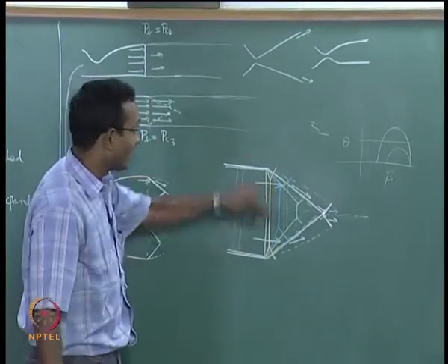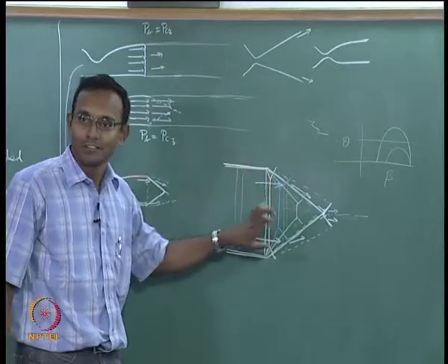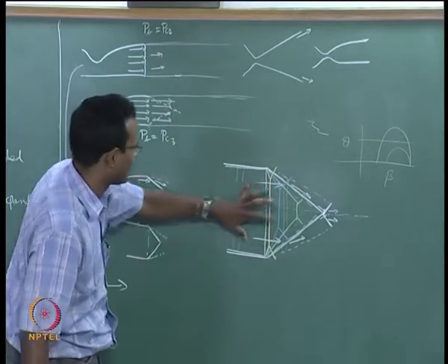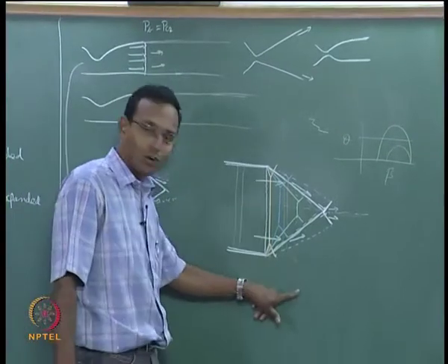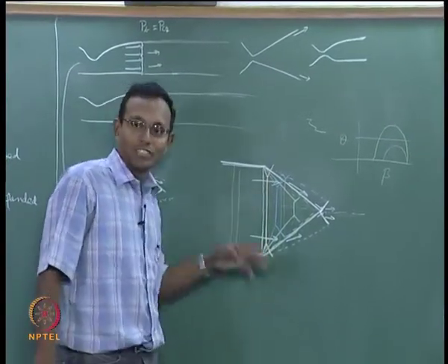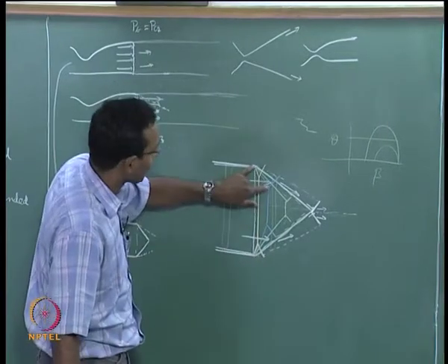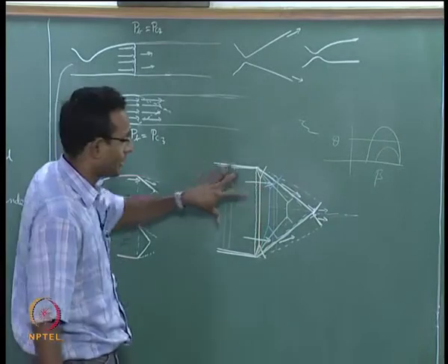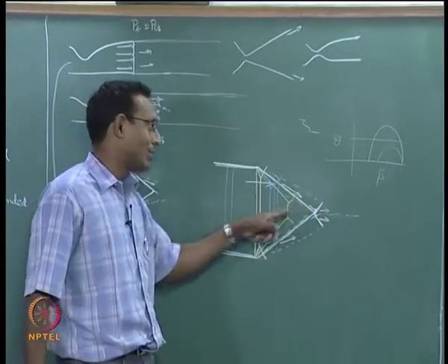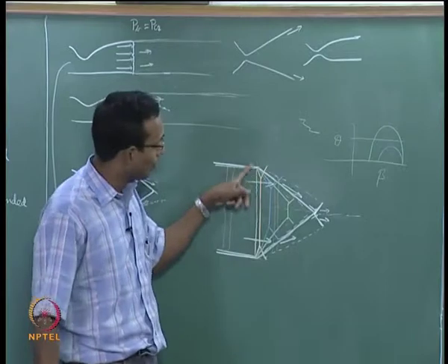Okay. So, on an average this slab of fluid has shrunk. When I decrease pressure more, it needs a lot more change. So, it goes to a point where more of oblique shock is happening, less of normal shock is happening, and it just continues like this. Eventually there will be a point where there is no more normal shock, the whole thing is oblique shock.